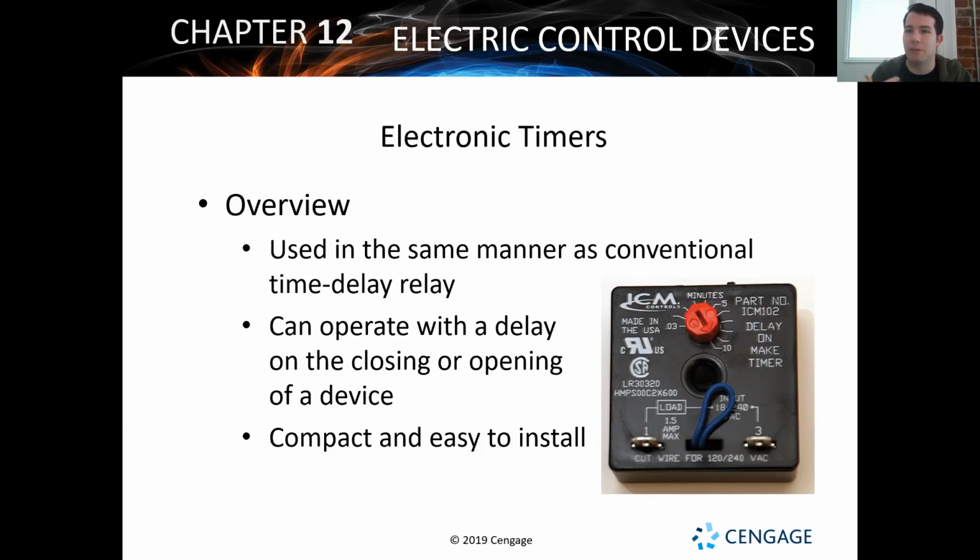And that's because it could be high amperage, could be high pressure, could be a lack of airflow, could be any number of problems, but this makes it so that we don't have the motors constantly trying to kick on, because the motors are going to try and solve the problem. Oh, it's not cool, it's too hot in the house. Well, let's turn all the motors on. Let's turn on the compressor and the condenser fan motor and the blower motor and get that cooling process to start.